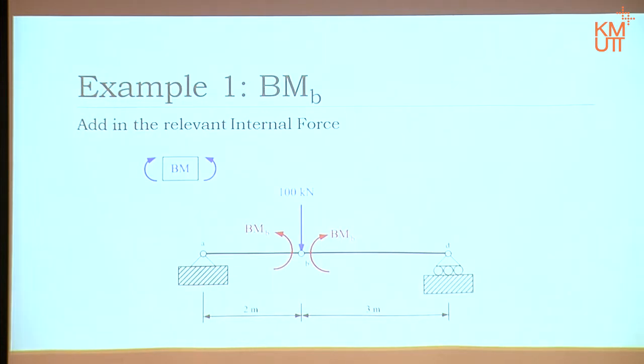Next, it is the same step as we did before. Next, we start displacing it in such a way that these two bending moments, or at least one of them, do the work. How does a moment do work? It has to rotate, correct? So the idea is that I will try to rotate either AB or BD. But because of the system, if I rotate AB anticlockwise, for example, then point B moves up.